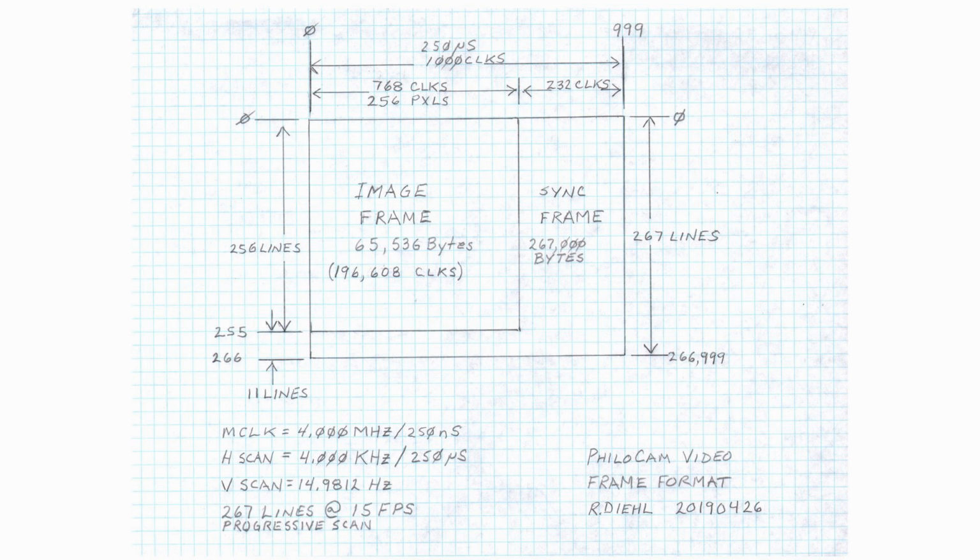so that each pixel clock of the frame memory, of the video memory, will occur every 3 M clocks, so that it is spread out 3 times wider. It makes up approximately 3/4 of the scan line time. This video format has a stupid wide horizontal blanking interval. It's almost 25% of the scan line. Nobody cares. It'll be fine. So we'll look at the schematic of that in a moment.